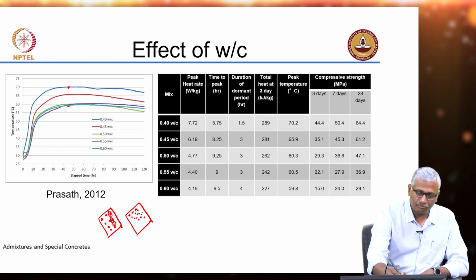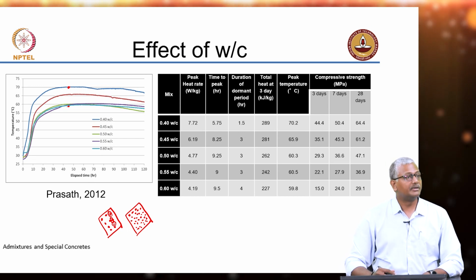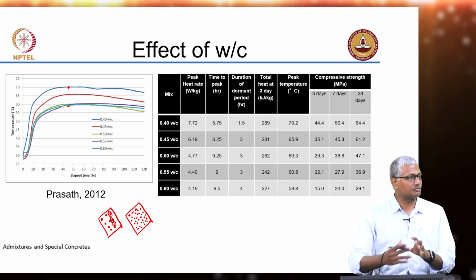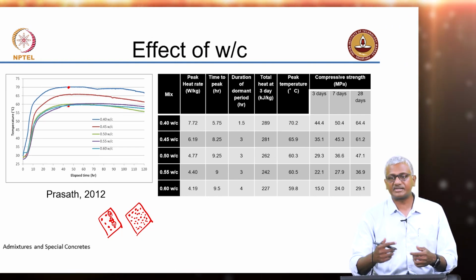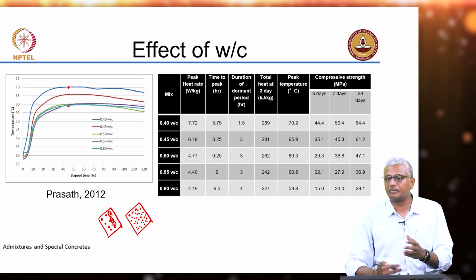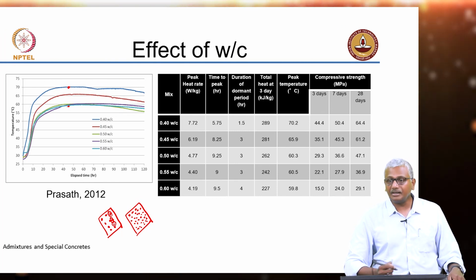So, for hydration to form bridges between these particles will be much faster as compared to when you have high water cement ratio, right. You do not have to have too much hydration for the entire system to start getting rigid. So, rate of reaction is much faster, there is more cement surface available for every gram of water that is available. Secondly,